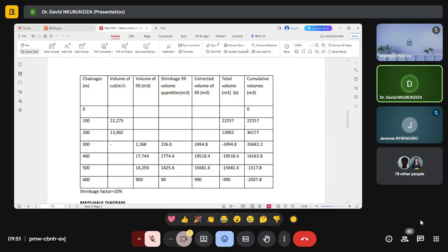If you dig a hole of 1 by 1 meter, so let us say you have 1 meter width, 1 meter length, and then 1 meter deep. After digging, if now it comes to the backfilling, you either have excessive soil, because the soil has gone through some kind of expansion.